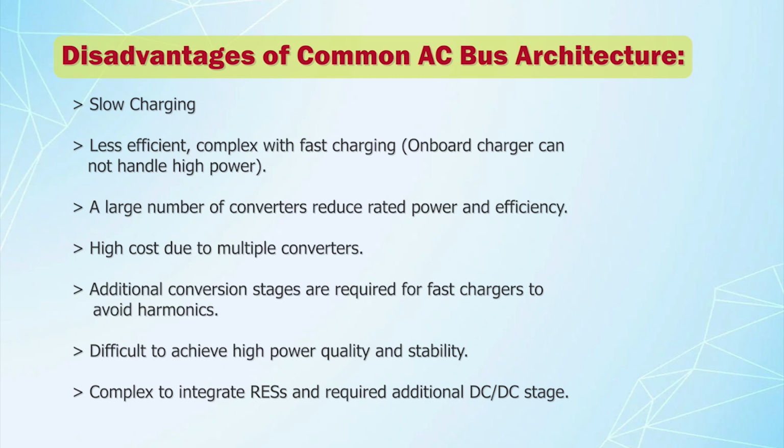It is complex to integrate renewable energy sources and requires an additional DC-DC stage, because a renewable energy source like solar gives DC power.